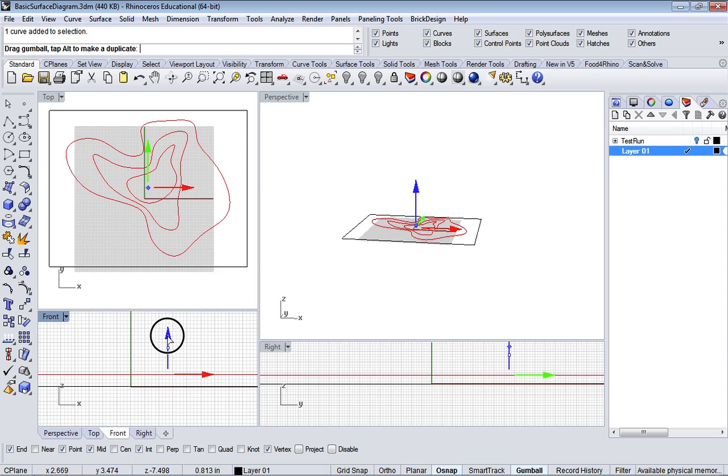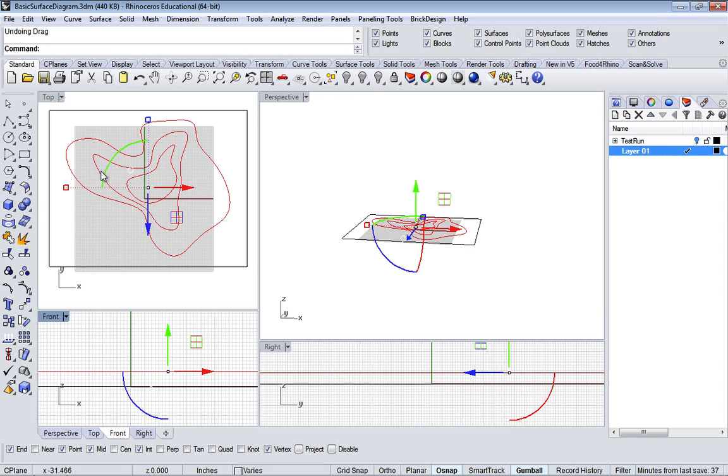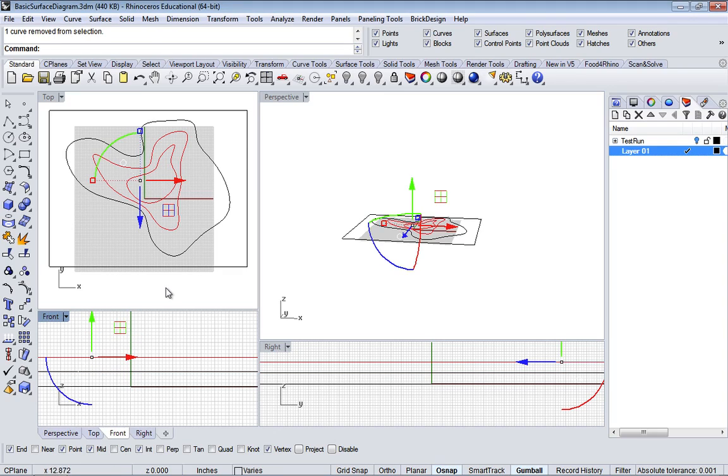So it looks about like 1 inch. So what I'm going to do is just click on here and type 1. All right, and I've selected all of these by holding down the Shift key. Now, if I want to deselect one, I hold the Control key down and click on it. So I'm going to click at the outside edge, and that deselects that one, but these others are still selected. Now I can go over here and double click on my blue arrow, which is the vertical arrow, and I can type in 1 again, and that will move those up.